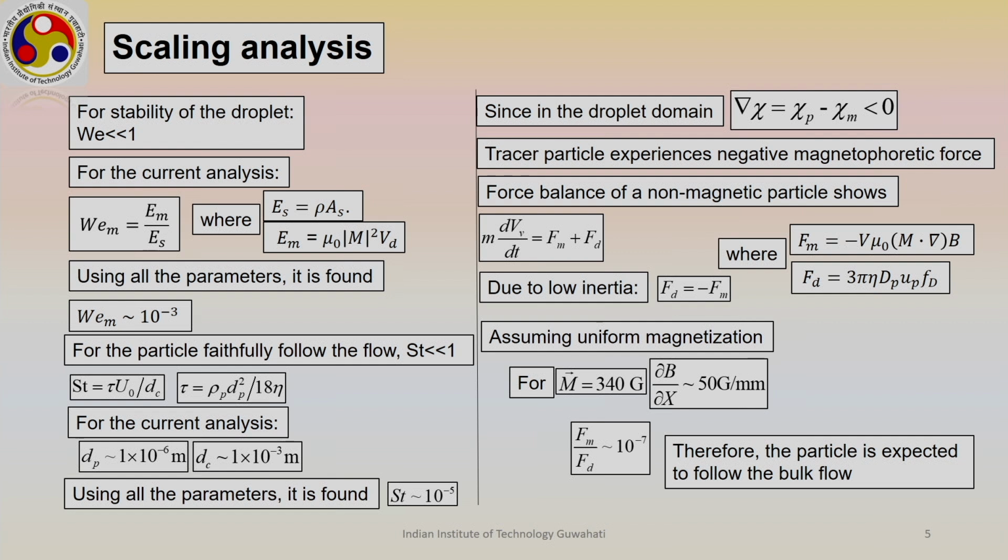Another important point is that our objective is to measure the flow velocities. The complexity in this analysis is that we have used magnetic nanoparticles, which will be perturbed under the influence of the magnetic field. The moment we switch on the magnetic circuit, magnetic nanoparticles will move towards the periphery close to the magnet, and because of this movement we get the flow velocity.